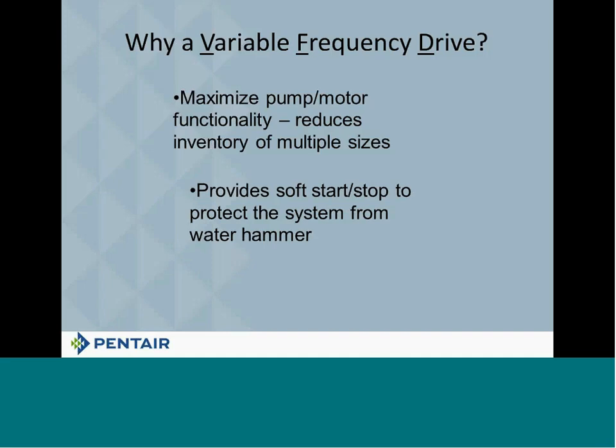Soft start means that what happens is we bring the drive up slowly. The drive brings the motor up slowly. With an above ground motor, it takes 5 seconds to get up to speed. A submersible motor is differently made, and it doesn't come in premium efficient. So a submersible motor must be to 1800 RPMs in 1 second. That's a rule with the submersible motor. So because it's a rule with the submersible motor, you need to make sure that you're at 1800 RPMs in 1 second, and that's what the drive will do.